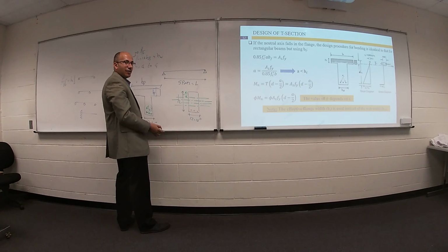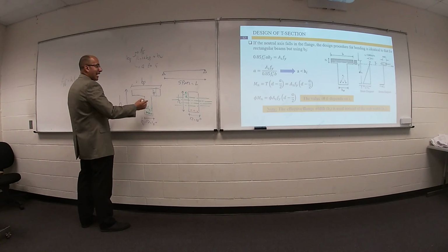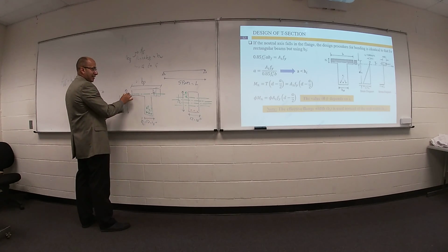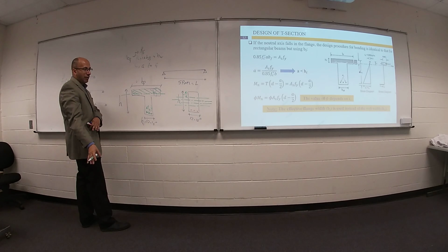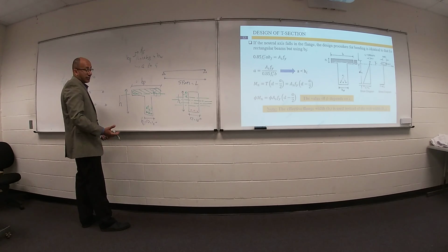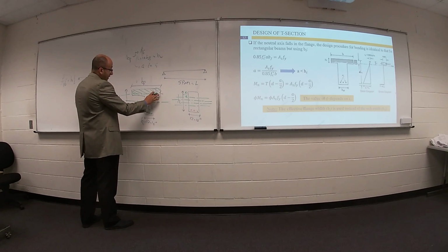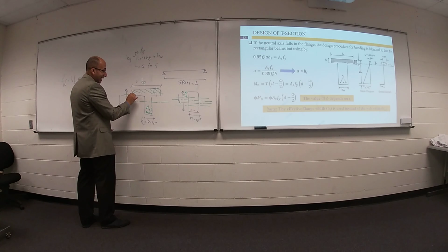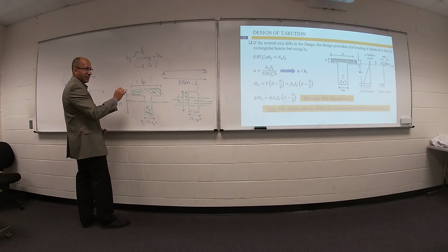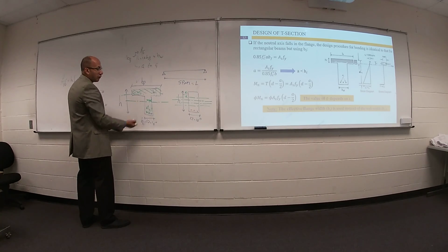But I have a problem here, because sometimes your neutral axis is here, so this part only is under compression and the remaining part under tension. Sometimes your neutral axis is here. Oh, it's a big difference. Because in the first case, your neutral axis is within your flange. In the second case, your neutral axis is within the web of the cross section.